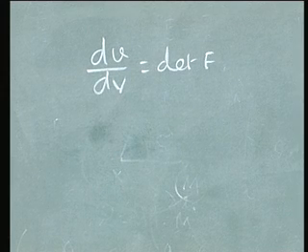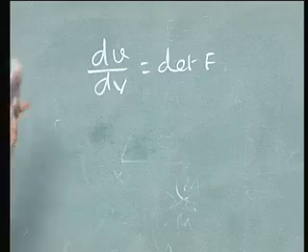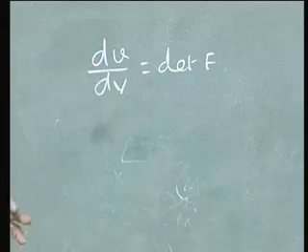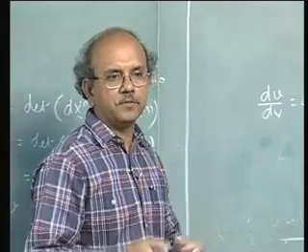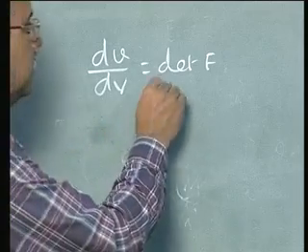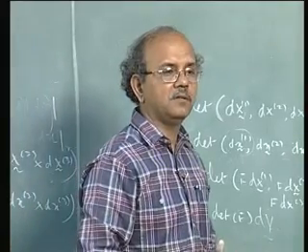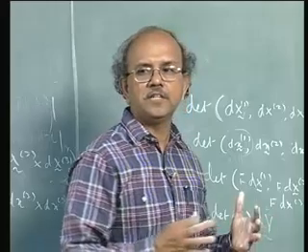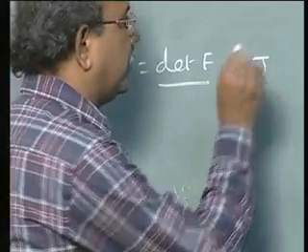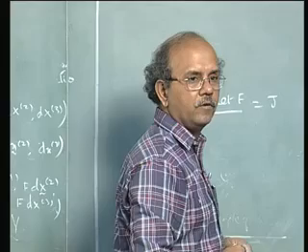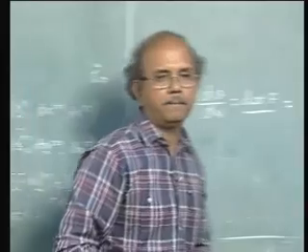Please note that all these material line elements are very small line elements, so you can say that this would give rise to that small volume change. Imagine that you want it to be a cube, and what happens to that. Now if the material happens to be incompressible, then what would happen? Small dv is equal to capital dV, or the determinant of F, many times written as Jacobian or J, happens to be equal to 1.